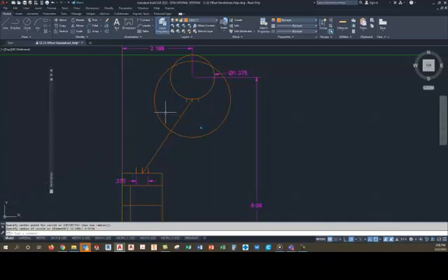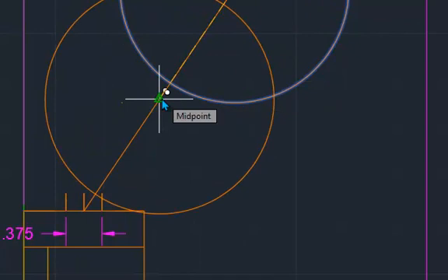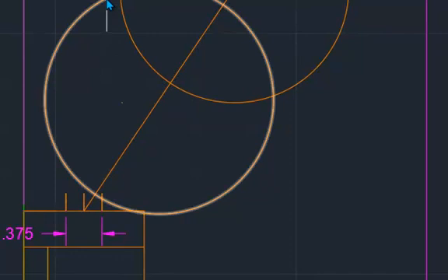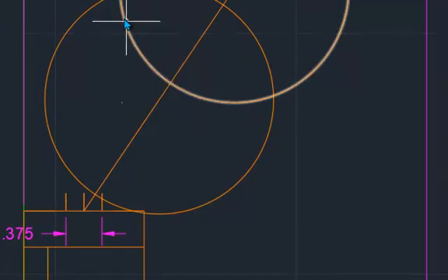So that being said, there's our circle. And the cool thing about CAD is I can use the copy command, and I can copy this from the center of it over to the middle of this right here. And you're saying, well, what good does that do? Well, I'm basically using a compass on the computer to draw an arc that intersects from the middle of this at my radius out this way, from this intersection right here out this way, and where the two arcs cross, X marks the spot. So that's my center point.